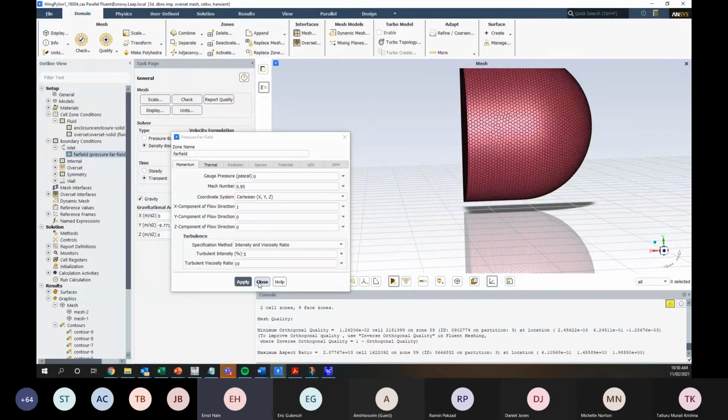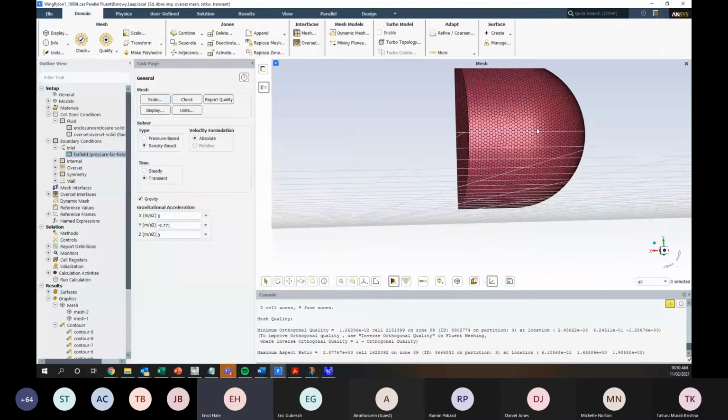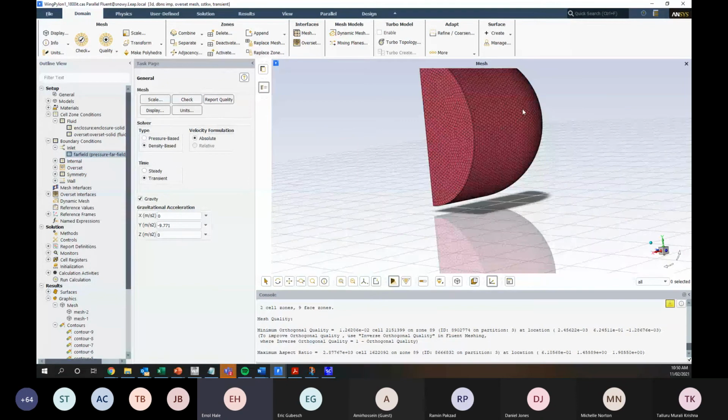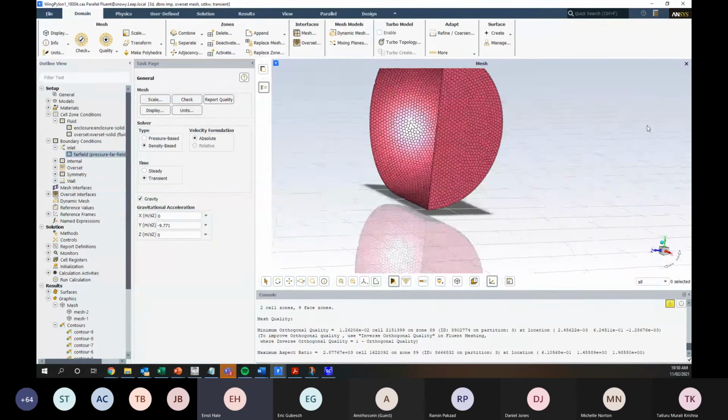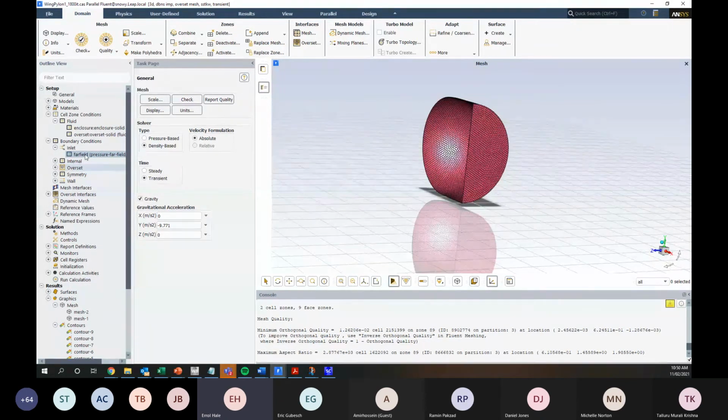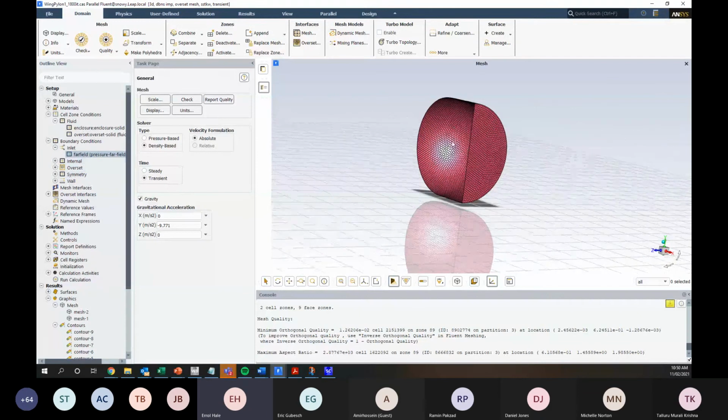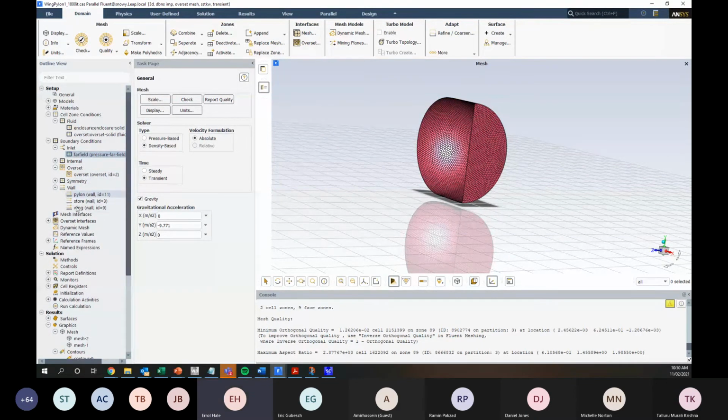This is really good any time you have transonic or supersonic flow conditions. A pressure far field is mathematically the best option. So we don't necessarily even need an outlet condition, because all of this just has the flow going in that direction. That's how a pressure far field is specified. This obviously is our symmetry plane, the center here. Everything else is zero slip wall.